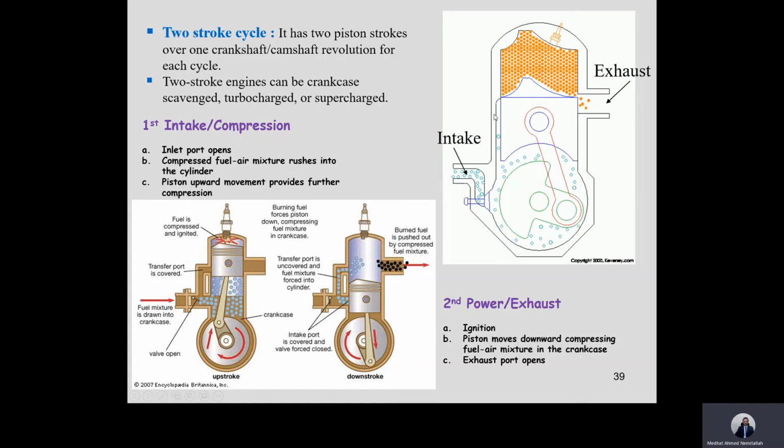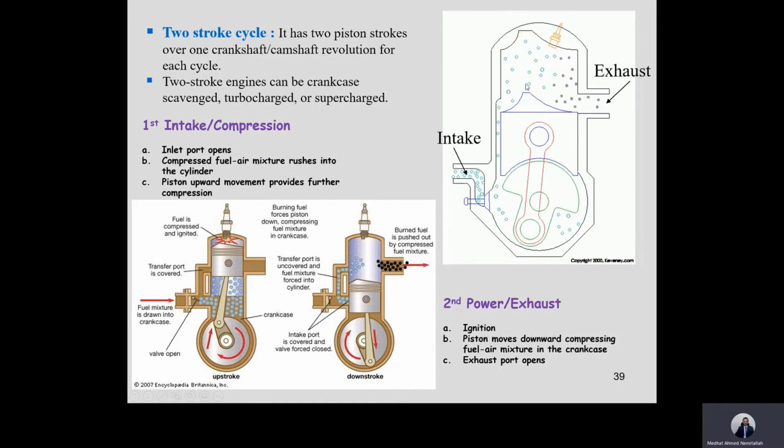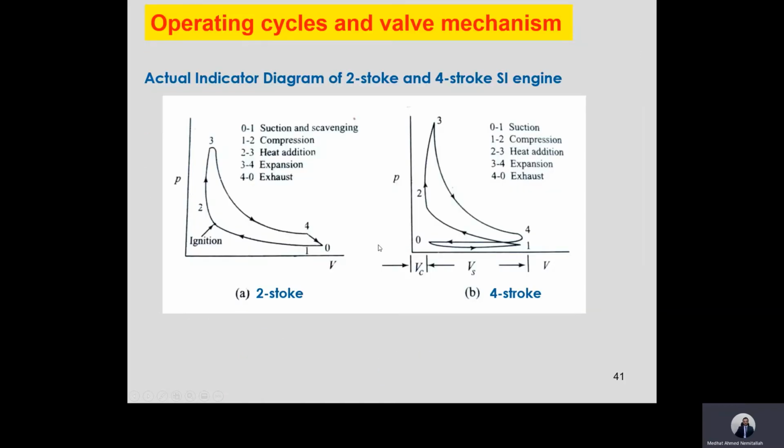This helps the air plus fuel to get inside the cylinder. And it also helps scavenge the exhaust gases, because while the piston is moving up, we still have some exhaust gases. So we have to force them to leave the engine. We call it crankcase scavenging.